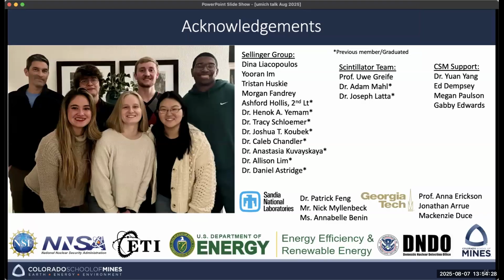There was another question about if any of these materials break during the casting process, can you reuse any of the components of the broken scintillator, or does that have to be scrapped? No, that's also the beauty of the organic glasses, they can be remelted and reused. With the PVT and with the silicones, if they crack during production, they're basically gone. You can't reprocess them. So that's another big advantage of OGS, that you can reuse them if they crack. Thank you.